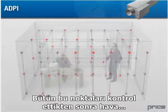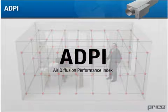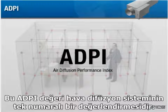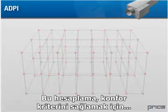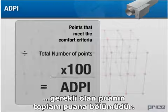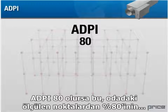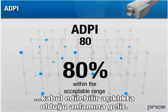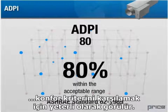After checking all of these points, an Air Diffusion Performance Index, or ADPI, can be determined. This ADPI value has proven to be a valid single number rating of an air diffusion system. This is a calculation of the number of points that meet the comfort criteria divided by the total number of points, times 100. An ADPI of 80 means that 80% of the points measured have air temperatures and velocities within an acceptable range. An ADPI of 80 or above is considered adequate to meet the comfort criteria according to ASHRAE